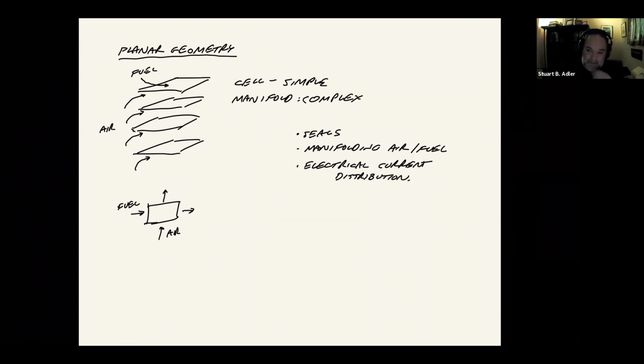So usually what developers try to do is, even if the electrodes are not perfectly conductive, you'll have some layer of material that acts as a current collector that can help distribute the current. And then you try to make contact at many, many, many points. So the current, as it comes down from one cell to the next cell to the next cell, is not being bottlenecked in any one spot. You're basically trying to maintain a wide uniform current density across the whole cell as it passes current to the next cell.